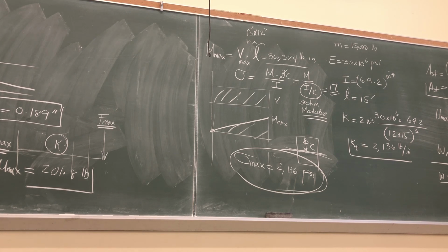So that shows sometimes, depending again on the R ratio and the damping ratio, dynamic stress can be much more severe than the static stress. So I thought I'd just throw in a little problem like this, which at least shows some application.